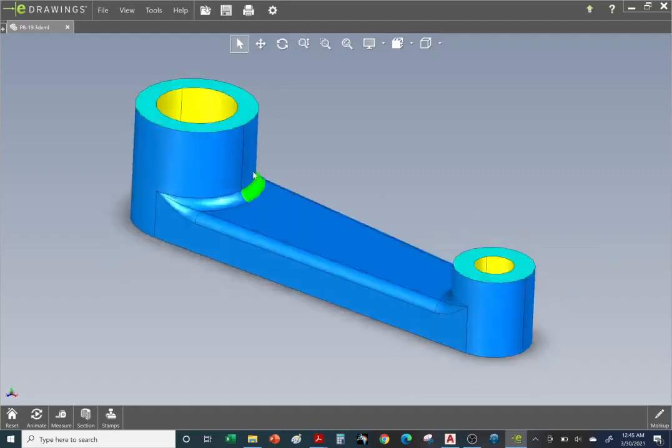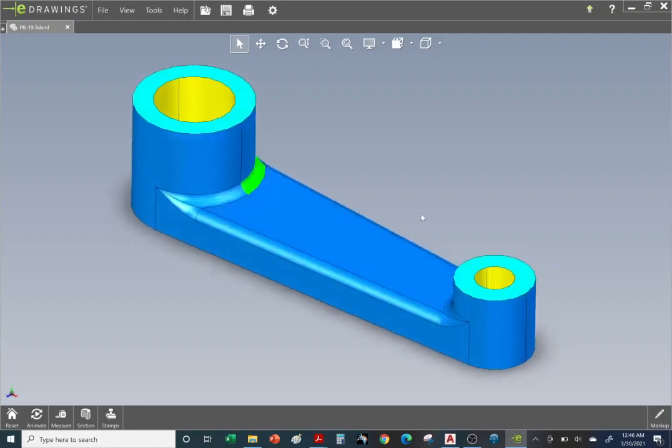a part like this is actually poured into a mold. Okay, so this would be liquid metal, and let's say it's aluminum, and it's poured into a mold. And once it goes from a liquid to a solid, all this has a rough surface. So everything will have a rough surface, rough texture to it. But this piece needs to be mated up to other parts. So this is something that you commonly see on a car, for example. It can be something in the suspension, or a good example is like a water pump.